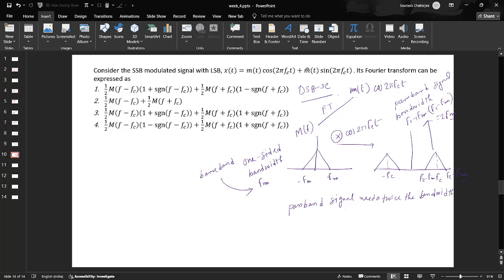And this is where the problem with double sideband suppressed carrier begins, because in wireless communication you can see bandwidth as a form of currency or resource, which is basically limited. So you always try to spend the minimum resource to achieve the maximum gain, right? But when you are using DSBSC, your bandwidth requirement becomes 2 times.